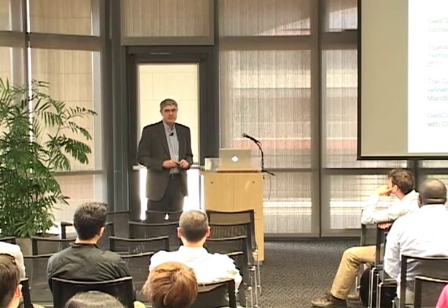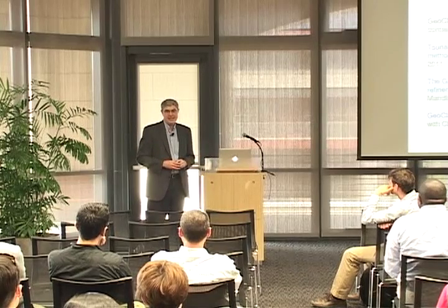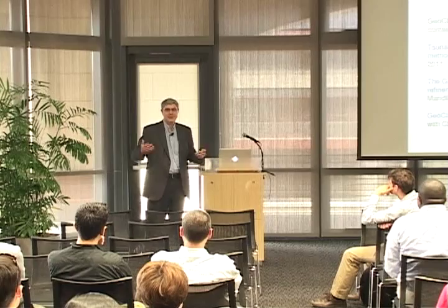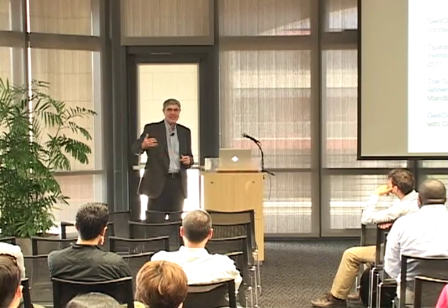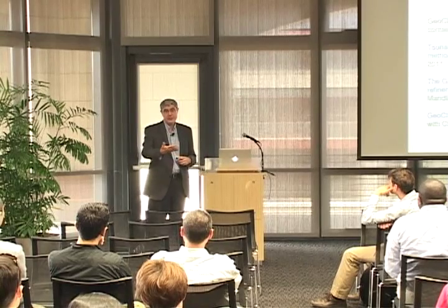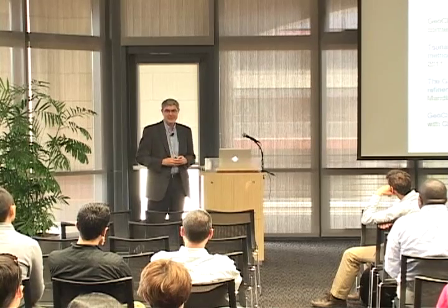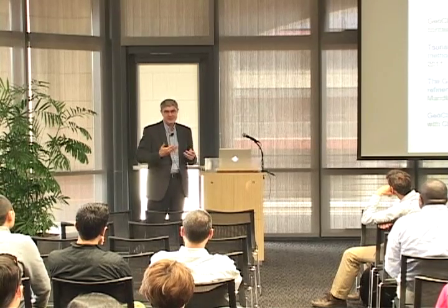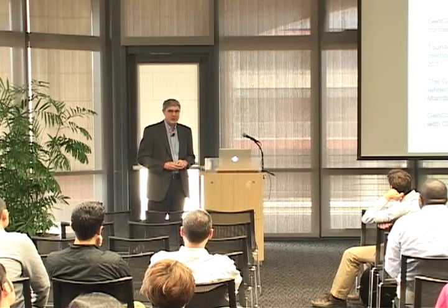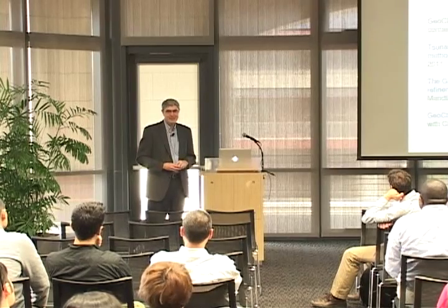For the tsunami modeling, for that aspect of it, there's a standard value of the Manning coefficient, 0.025, that people typically use, which is flow over gravel or something. It's a worst case of a tsunami coming in on bare land. I should also say that the topography that we use on shore doesn't have structures in it. It's the bare earth topography. So there are a lot of questions about the accuracy of this inundation model compared to what's really happening when you have structures. And of course, the structures may get knocked down, and then it becomes a debris flow and becomes much more complicated.